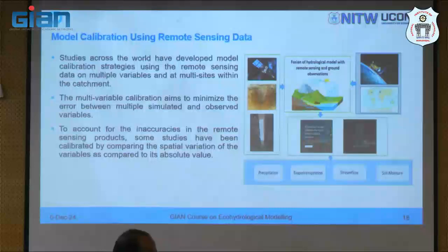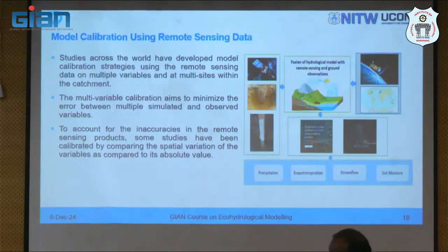So when you do calibration process, and now most of us are doing an automatic calibration process, your optimizer will give you different combination of parameters giving similar result, or in some cases same result, right? So if you go back to your ESCO and EPCO values, let's say a performance of 0.8 or 80% accuracy can be obtained with an ESCO of 0.5 and an ESCO of 0.8 or 0.9.